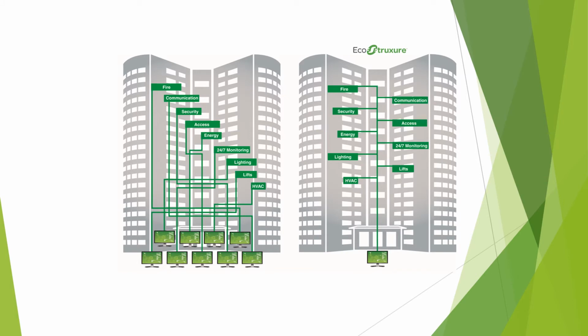In the past, it was not unusual to monitor systems in your building, such as HVAC, lighting, or fire, from several separate platforms, sometimes called multi-silo systems. Today, with device-level integration, we are bringing all the building systems together within the BMS. This data integration allows for a single access point to monitor and manage alarm handling and data acquisition. Sometimes these are referred to as multi-silo systems, and here we show it as an integrated solution.